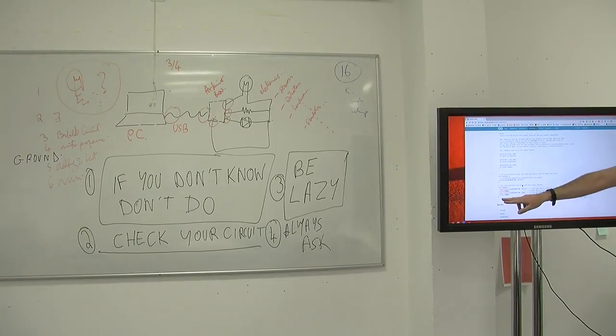So we copy and paste this program, which is from here to here, and then we check. We have an option on the Arduino IDE to check the program, and then what's the sixth step? Right. We run it, and in an ideal scenario, you should see the LED blinking. Okay? That's basically what it's all about.